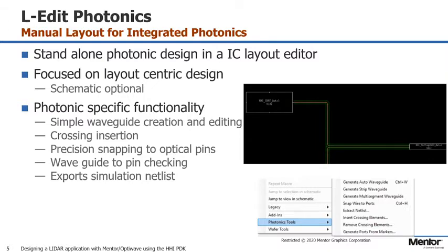And then what we've added is a set of photonic features that make it easier and more productive for photonic designers to get their day-to-day jobs done. Some of those features are waveguide creation, crossing insertion, snapping, as well as pin checking. And then we've exported the circuit into OptiSPICE to do your verification, so you don't have to worry about